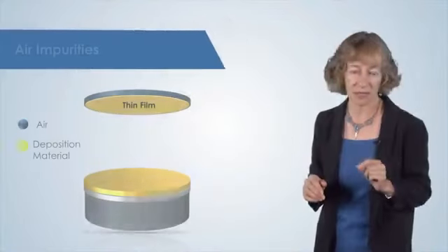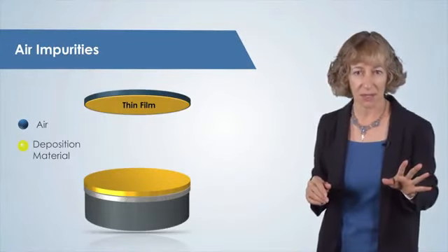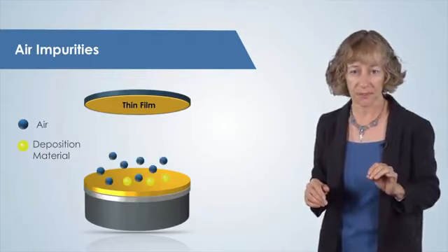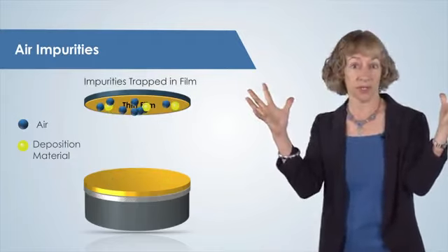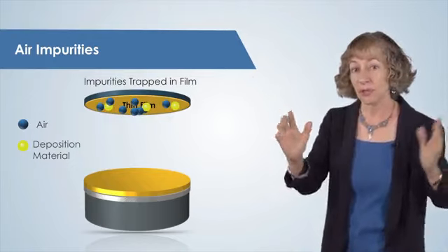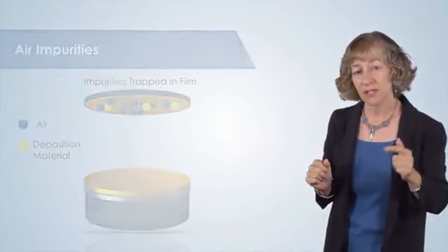But a clean room alone is not sufficient for our thin films. Most of these nanofabrication techniques are extremely sensitive to any impurities and contaminants, which also decrease yield. These processes are so sensitive, in fact, that the air itself could result in defects that affect the purity of our thin film coatings. So this leads to another requirement for depositing thin layers of high purity materials. We deposit the materials in a vacuum system.